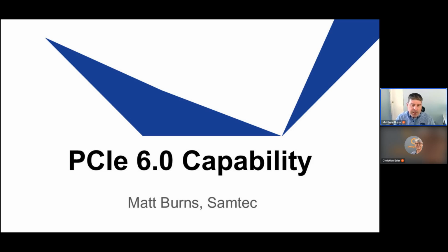Now, when the original COM-HPC spec was created, there was a lot of SI work put forth to enable PCI 5 capability, but we want to show how implementers right now can leverage the SI hooks, if you will, within the COM-HPC spec and within the COM-HPC carrier design guide to design future-proof systems for PCI 6.